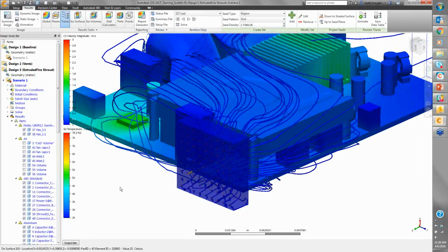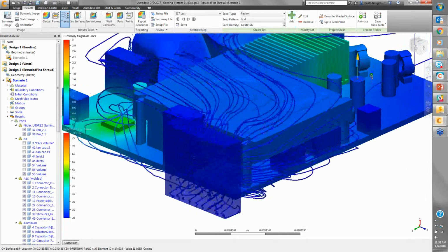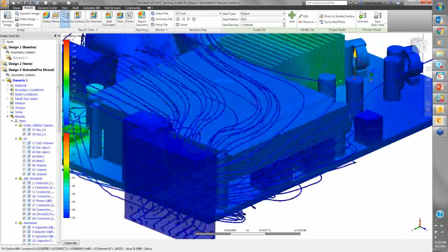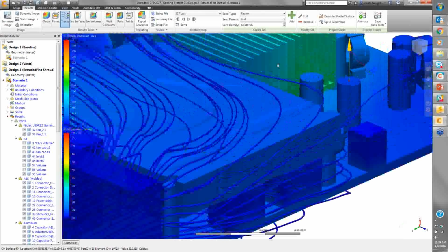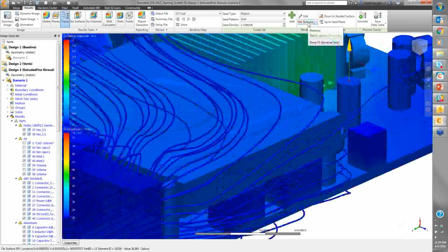So I hit region, and it's on a face in the model. Let me show you what I mean by that again. So let's say I wanted to add, for whatever reason, the region on the top of this cylinder. Well, that grid spacing happens to be so sparse that it only did one. So that was a fail. I didn't preset my sizing.